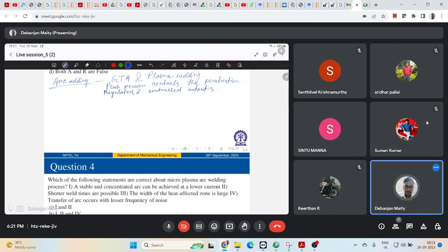Then, in terms of laser and plasma in microjoining, in laser welding you have an intense laser light which rapidly heats up the material in the order of some milliseconds. It is basically a non-contact process where you have very little distortion of the final joint geometry and a narrow heat affected zone.